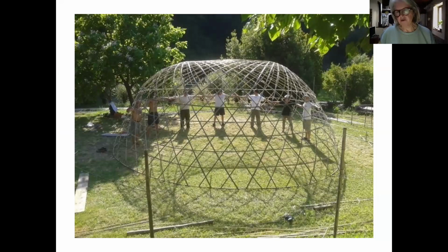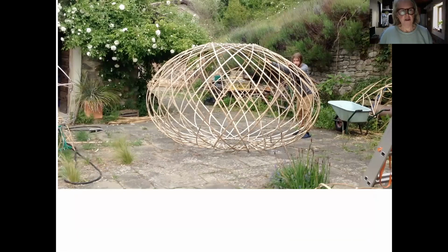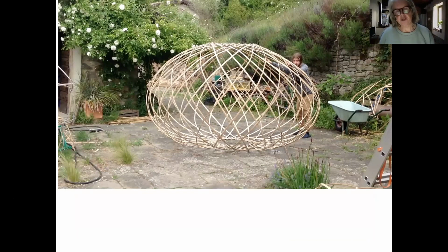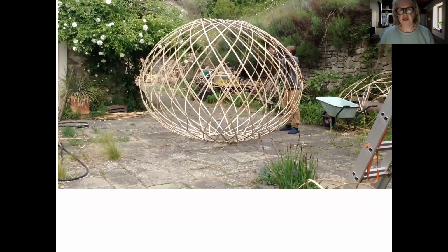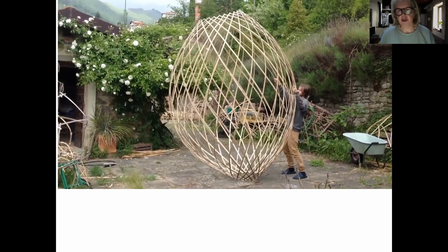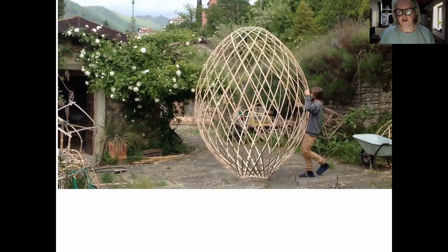So the issue with this sort of structure is that it has to be built on location. You can't transport it, obviously, when you get to a site of this kind of dimension. So one of the issues I've been working on is to make things more transportable, looking at how things can be compressed. Here again, if I assume that this style of weaving is similar to a cylinder, which is deformable, as well as weaving, I'm using nuts and bolts to connect the elements, and then the sphere shape can be deployed into a cylinder. So it's quite compressible and would fit on the back of a truck. So that helps with the transport issue.